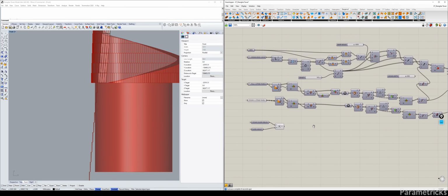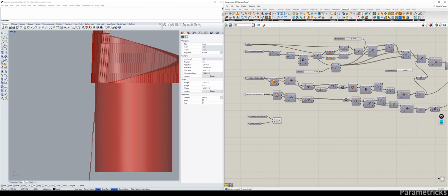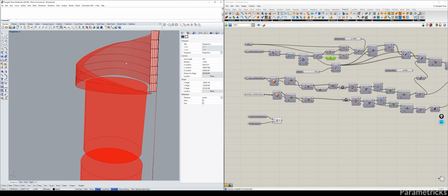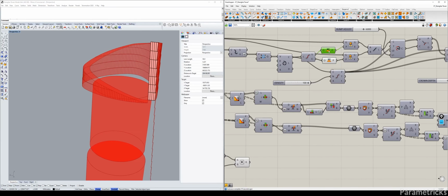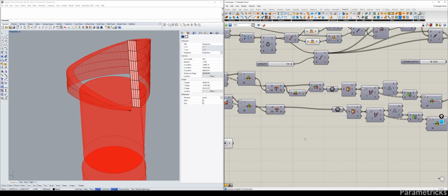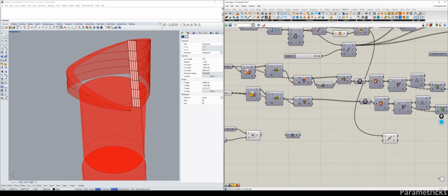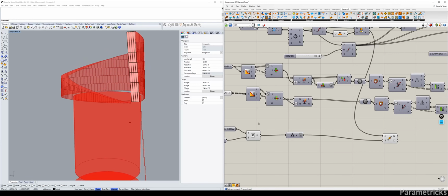And what we're gonna do now, since we have those, we can reuse that. Let me see. I do want starting one. Yeah, that one. So I'm just gonna quickly say move that plane down. This one, the z-axis. Let's do a minus z because we want to move it down. So we've moved it now down by 2 floors. Okay.